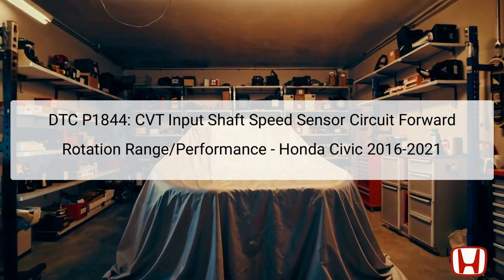The DTC P1844 pertains to a malfunction detected in the continuously variable transmission (CVT) input shaft speed sensor circuit, specifically indicating a problem with the forward rotation range or performance. This diagnostic trouble code, DTC, is significant as it directly affects how the transmission control module, TCM, reads the rotational direction of the drive pulley.